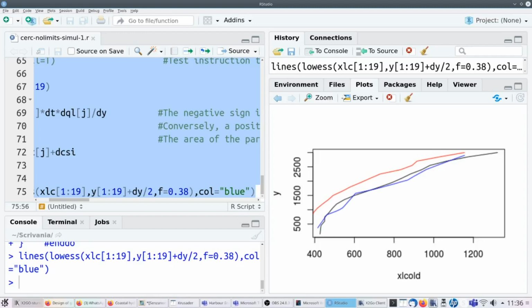how these algorithms work. Actually, there are commercial softwares which do the same thing, which are more accurate because they have checks for instability, and they may also use several sediment transport formulations, because one reason here for instability may be that the CERC formula is not reliable in estimating the longshore sediment transport.